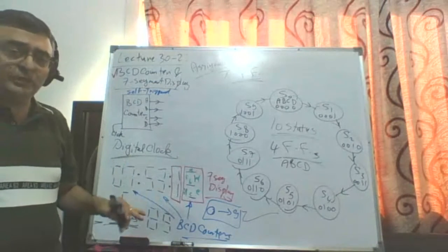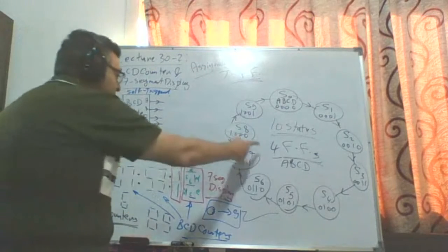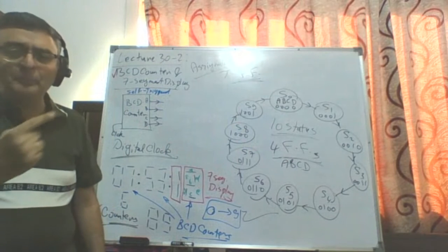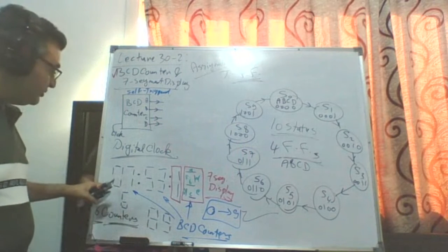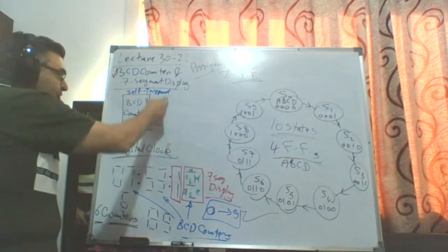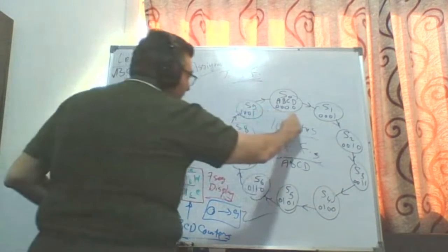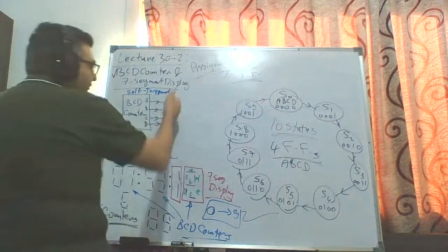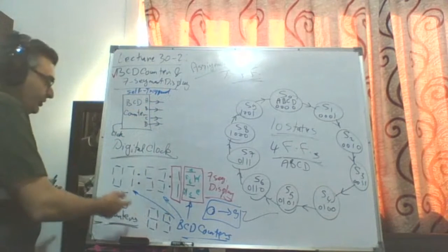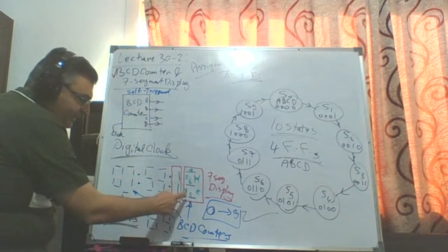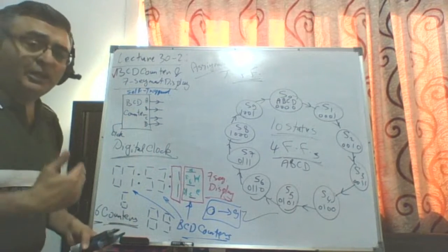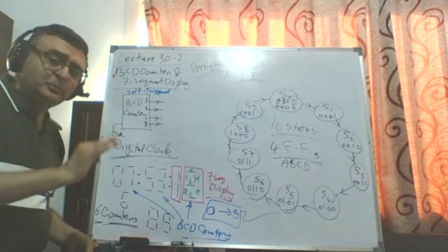So today we wanted to learn. Now we learned what is the digital, what is the BCD counter. The BCD counter is producing 4 binary values for the number to be displayed. So for number 0, here I will have 0, 0, 0, 0. But I wanted to convert the output from the BCD, for the count 0, the outputs of the flip-flops will all be zeros. I want to convert this binary, all zeros, to translate it to everything being on from A till G except the middle one. How can I do that? I can do that through a combinational circuit called the 7-segment display decoder.